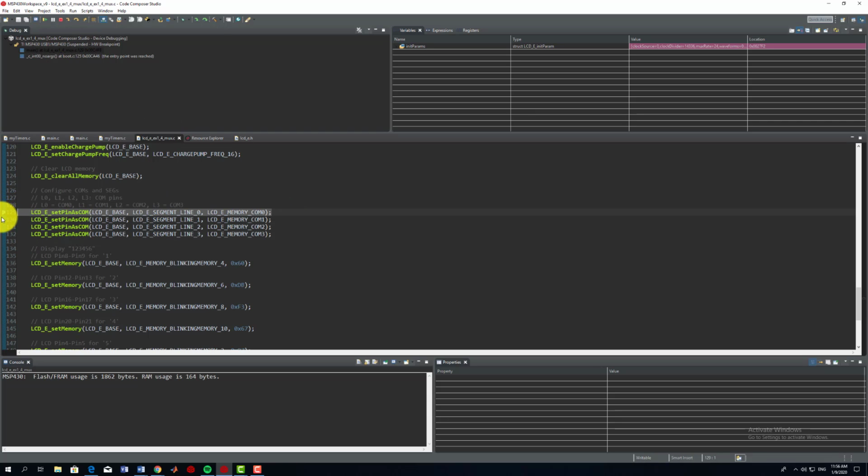For this one, because we have the breakpoints, we can just click again and we can see it. It should be seen on the screen of your MSP430FR4133 that the string 1, 2, 3, 4, 5, and 6 are blinking.